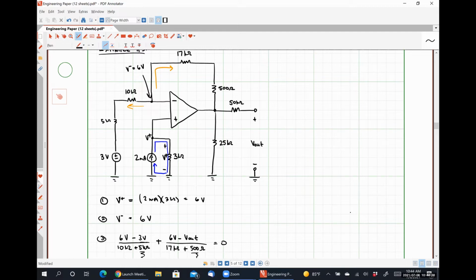So does the fact that there's a 50 kilo ohm resistor between this node and where we're measuring V out change your answer in any way? Effectively, what I am suggesting is that you are assuming that our voltage V out occurs at this node here in the middle that I'm making real big, when V out is actually defined to be this one.